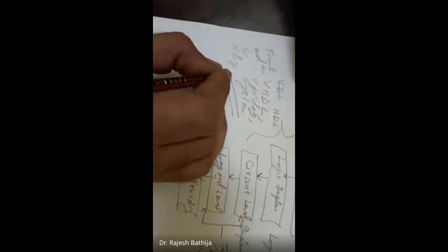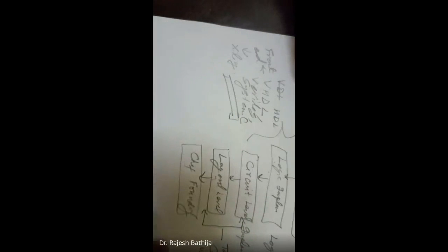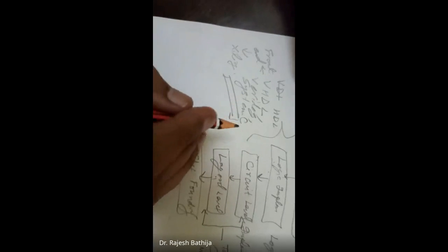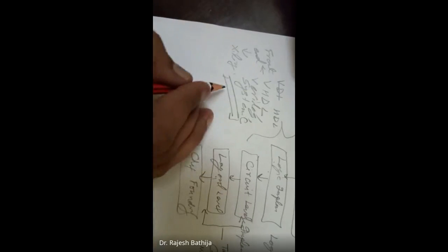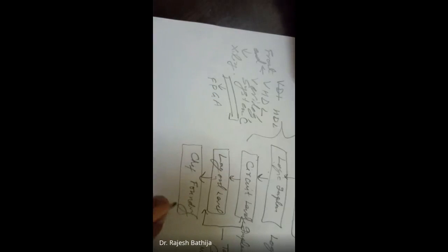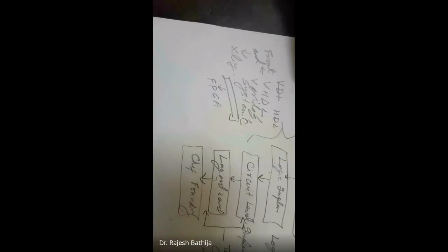So first we have to check it in the software, and these software languages are VHDL, Verilog, or System C. In these languages, it is easy to change the program, and then that can be burned on the FPGA to check whether my design is right or wrong. If it is right, then we can proceed to the next level, that is the circuit level or the layout level.